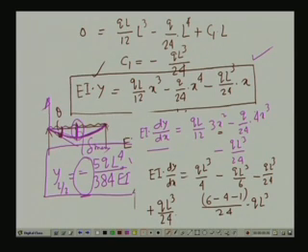Now, if you take a tangent at this particular point, the rotation here again is in an anticlockwise direction, and according to our sign convention, this is positive. So, theta B is equals to plus qL cube by 24. So, we have theta A computed, the theta at support A and theta at support B. These are the aspects we were required to compute. We have computed first the equation of the deflection curve, and consequently the deflection at the center of the beam, which is the maximum deflection in this particular case, and consequently the rotation at A and B as the support points.